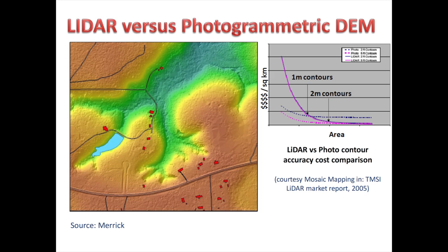So for example, here we have an air photo. I apologize, it's not a particularly great air photo, but it serves to illustrate a point. Now from stereo pairs and traditional photogrammetry, we can generate a triangulated irregular network model of a digital elevation model, strip away the vegetation. But one of the problems in forested areas, of course, is that the ability to see the ground beneath the trees is somewhat limited. And so we end up with what we can see here, a fairly faceted model, fairly low resolution representation of the ground surface.